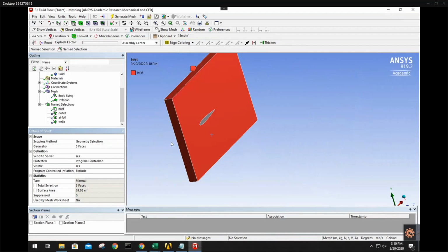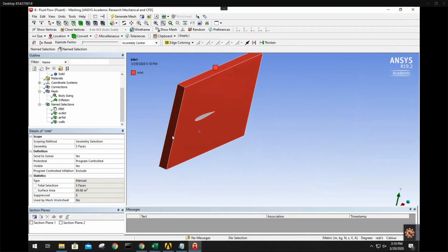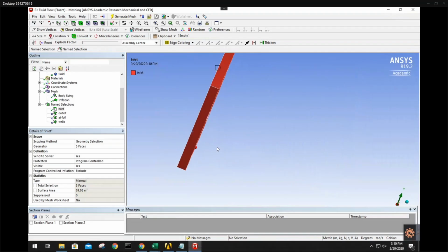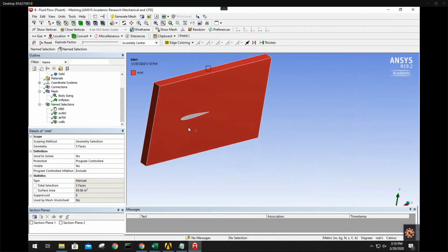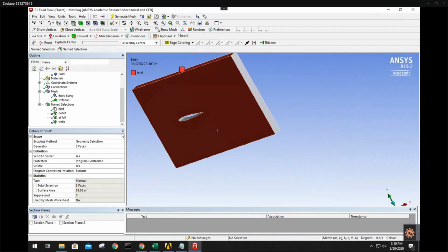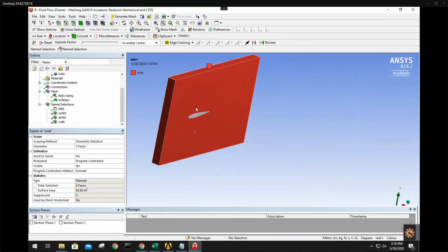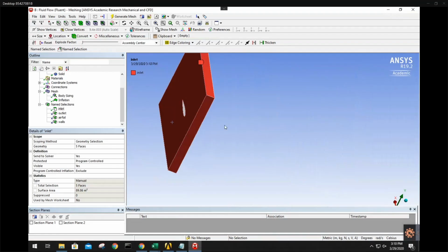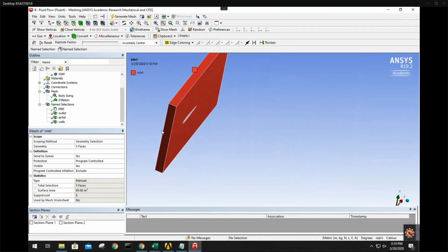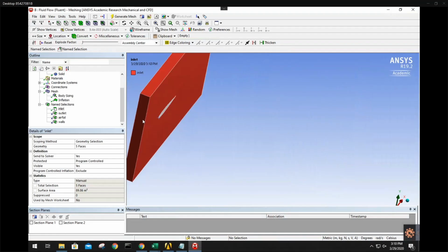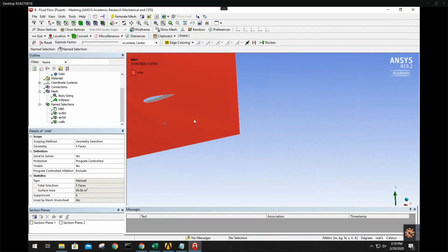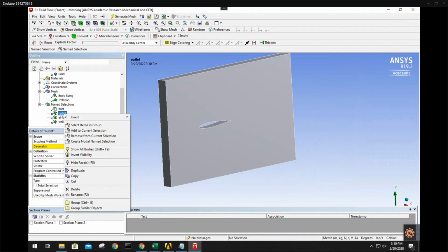So I think this actually should be okay, because flow into the screen here or flow here doesn't matter. Actually this would probably be better, because if I set these parts to walls, it might mess up the fact that I'm going from a velocity inlet to this boundary condition being 0. It might be a little bit weird. Don't know. This is my first time trying it.